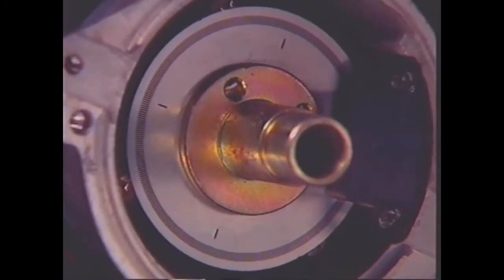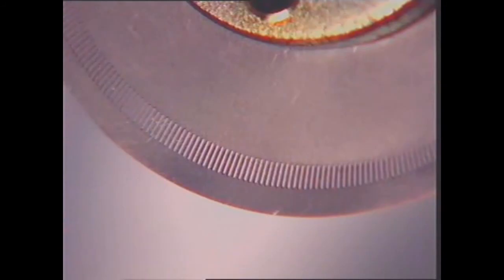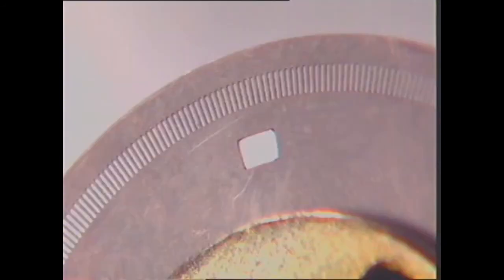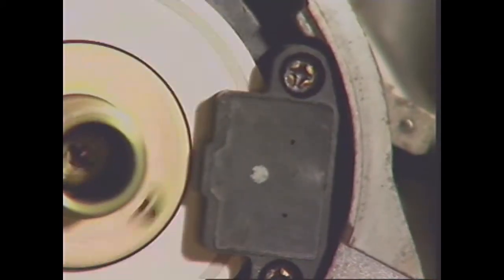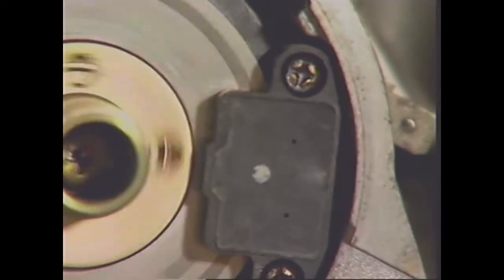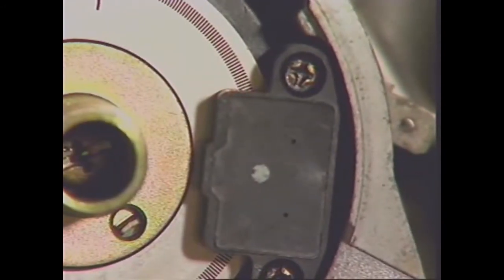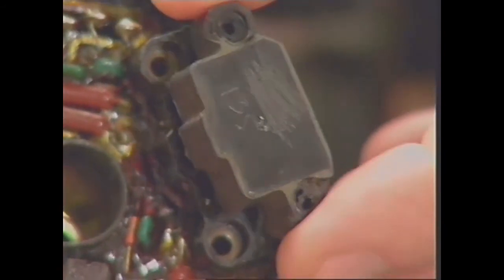In this type, a signal rotor plate is attached to the distributor shaft. It has 360 slits at 1 degree intervals on its outer edge. Inboard of these slits are 4 slits, 1 for each cylinder. One is larger than the others to provide a signature effect for number 1 cylinder. As the rotor plate turns, it passes between 2 sets of diodes positioned in line with the slits. The diodes above the rotor plate are light emitters.